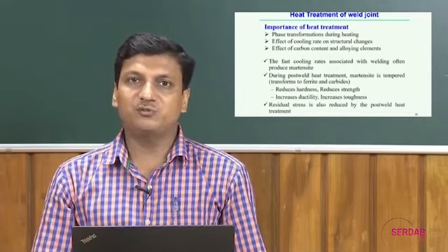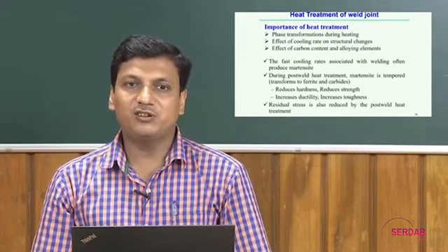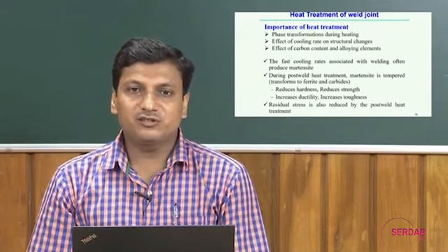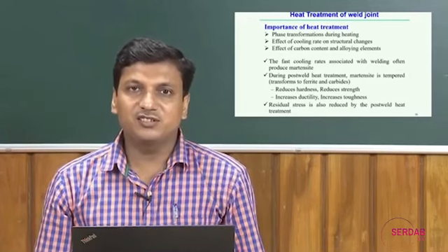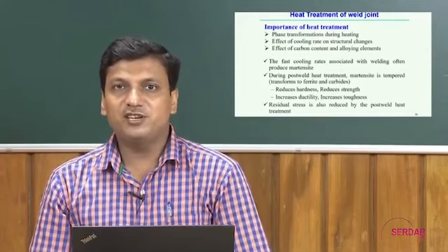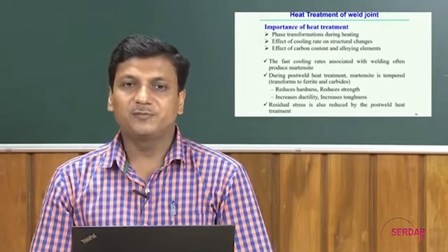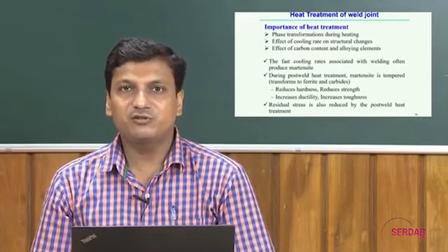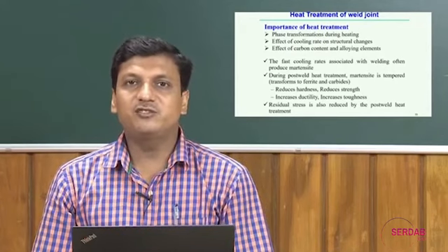So, during that transformation, its overall impact on the weld joint properties is that it reduces the hardness, reduces the strength, but increases the ductility, increases the toughness. So, that is the benefit of the heat treatment process in any case of the weld joint. Of course, residual stress is also reduced by the post weld heat treatment process.